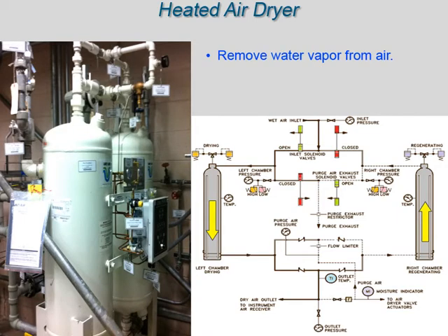Air dryers remove water vapor from air without condensing the water. Air dryers are normally used for instrument air systems. Desiccant or absorption air dryers are the most commonly used for instrument air systems. Desiccants are chemicals that readily take up and retain moisture on their surface.